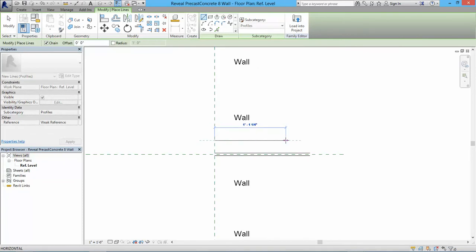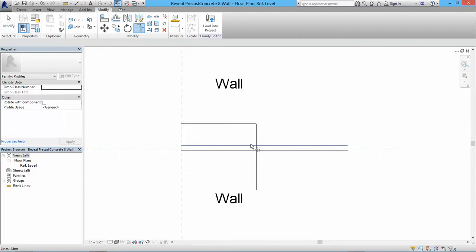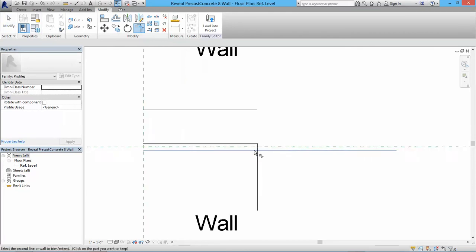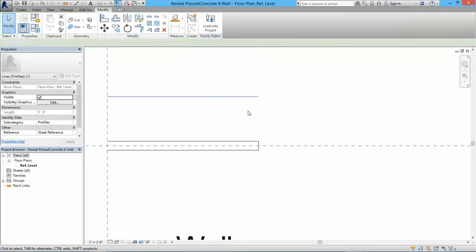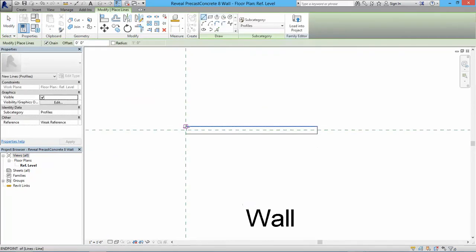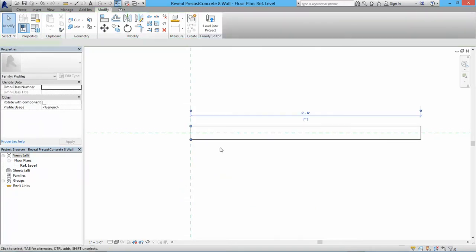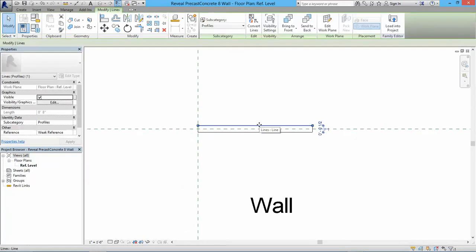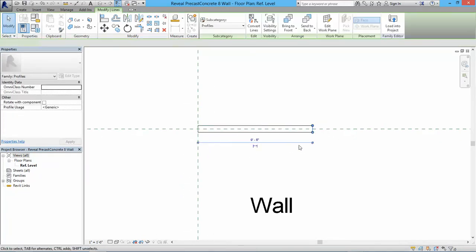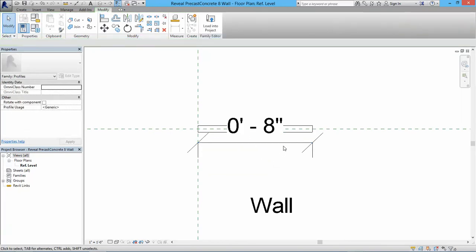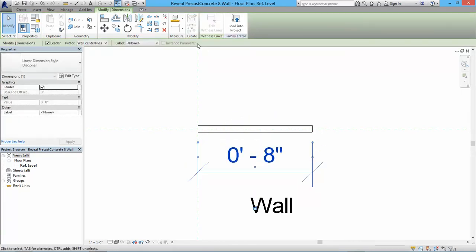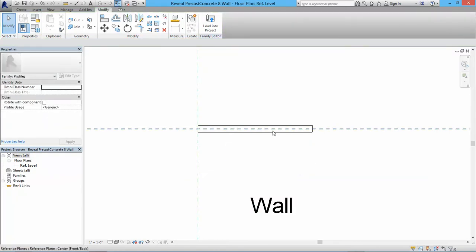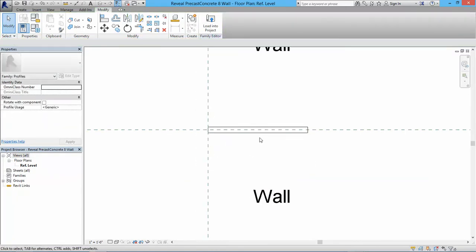Again, you could do more, like 8 inches here, take it down, trimming, TR, trimming, delete, and it has to be close, so that has to be generated there. You could do some very simple parameters, like, for example, selecting this guy, given the length there, and creating a new parameter, and you can change that depending on the wall that you have. But in this case, we're going to just stay put with 8 inches, so that should be fine.